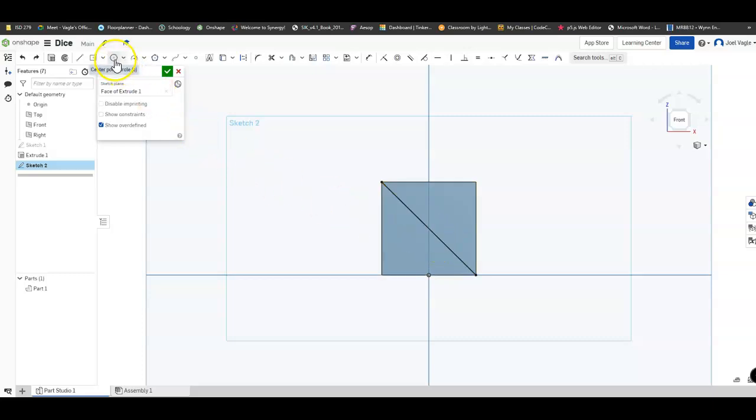So I didn't have to draw that second line because there's this cool little feature here. I went back and turned on my circle again. As I mouse along this line, watch what happens when I get close to the middle. That square pops up. That orange square is telling me I'm at the midpoint of this line. This feature works on lines along the top. See, there it is there. Along the sides, and along diagonals.